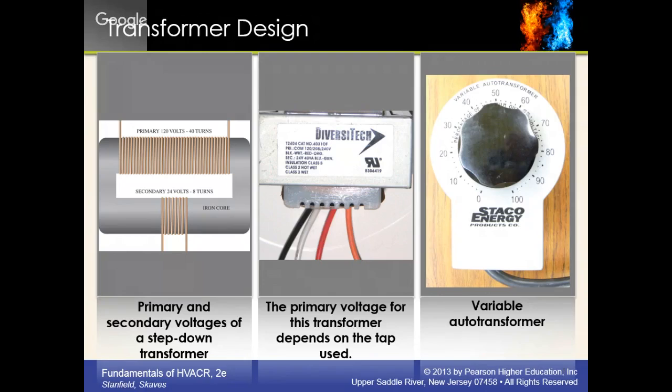So if the diode, let me draw it up here. AC to DC. Yep, it's used for that. A very common place is in a rectifier. On the low voltage side of your transformer, when you're converting 120 to 24, and then you needed a DC part, DC 24, you could put a rectifier in, and it would be 4 diodes in kind of a diamond looking shape. We could talk about that all day long, but we got to test it.